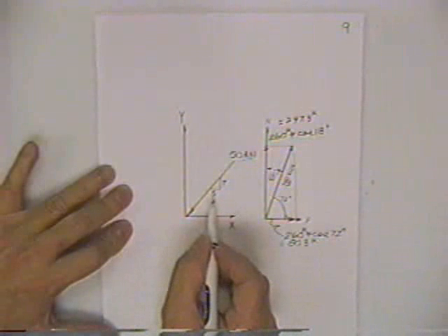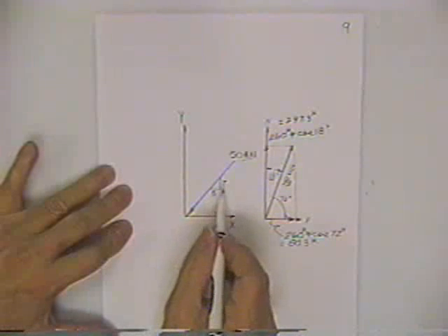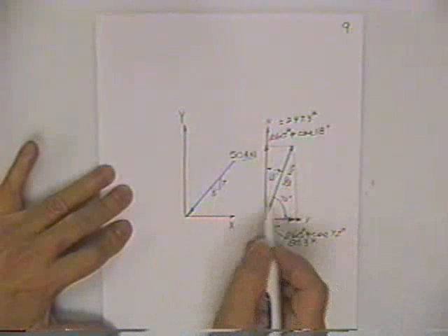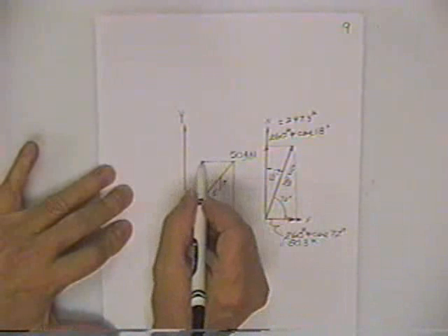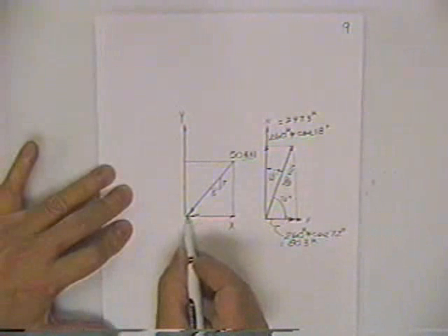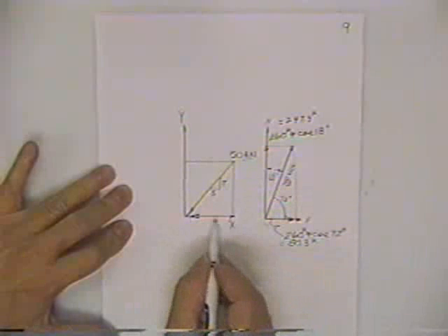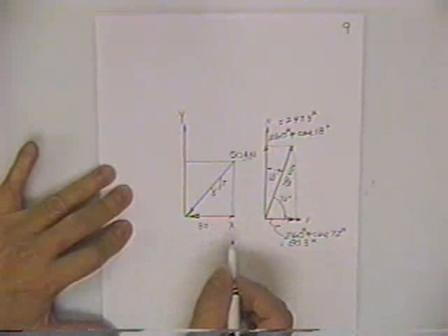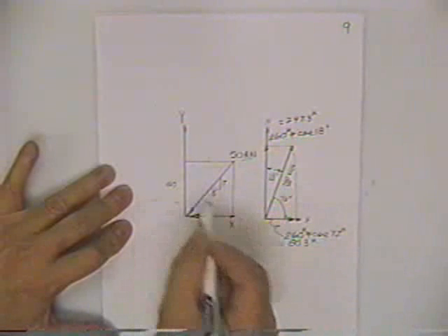Now, another way of asking you for components of forces would be when you know the slope of the force as opposed to the angle at which the force sits. Again, I draw a box around the force, and without any help from a calculator, if this thing right here is 50, then I'd say that number there looks like about 30. So I ought to have some feel for what the number is. And if that's 50 and that's 30, this is maybe somewhere around 40.